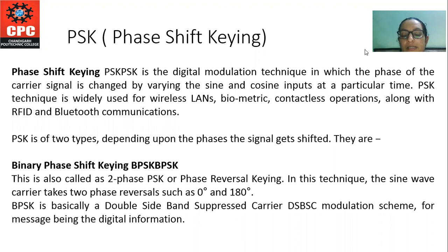The PSK is an M-ary digital modulation technique similar to the conventional phase modulation except with PSK the input is a binary digit signal and there are a limited number of output phases possible.